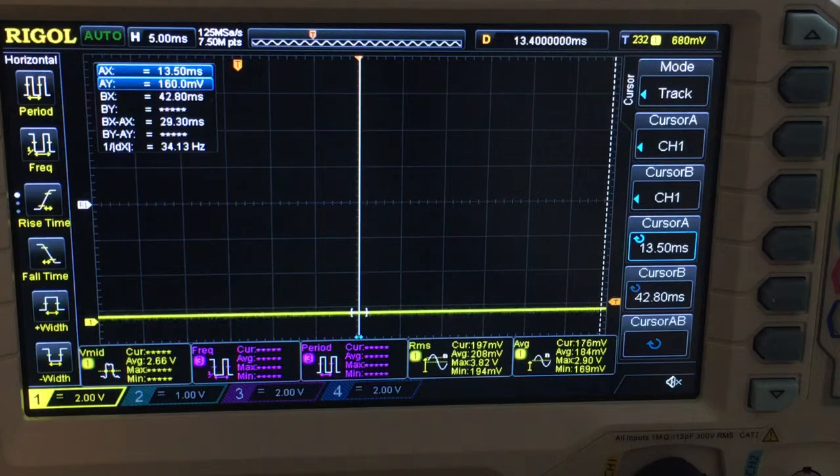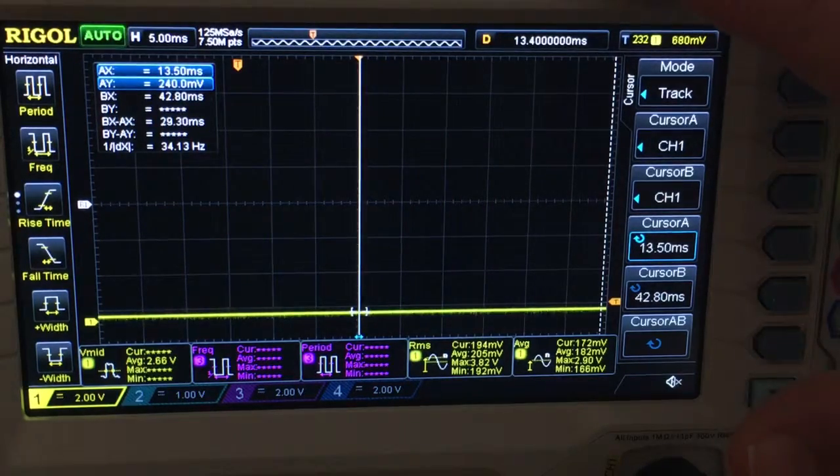So we're talking about TTL control, and I've described the method of control wherein the signal output from whatever device you're using, whether it's a trigger scope or a National Instruments board or any other device, is going to output a voltage. And we're going to measure that voltage using any number of devices. We can use another piece of hardware like a shutter controller or a laser, or we can use a piece of hardware like, in this case, an oscilloscope.